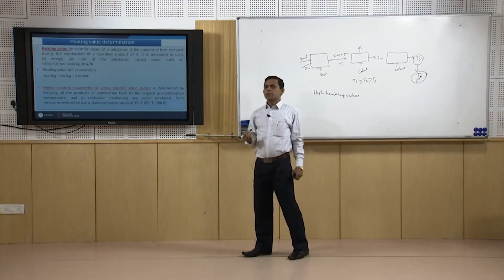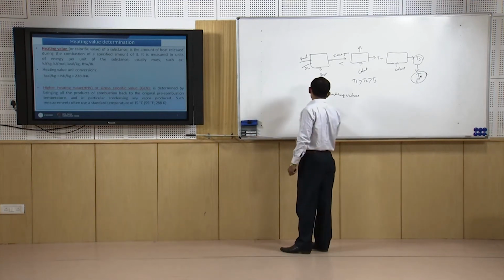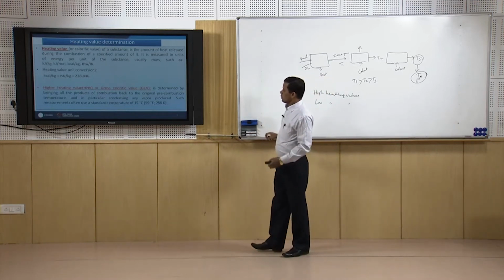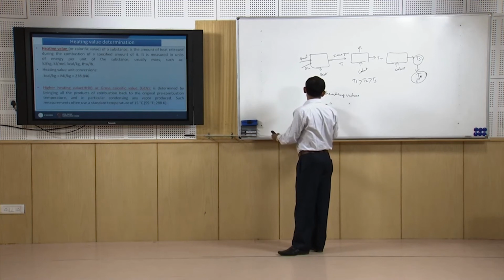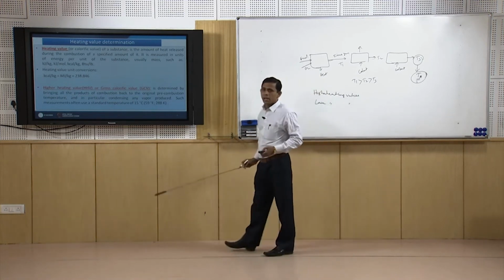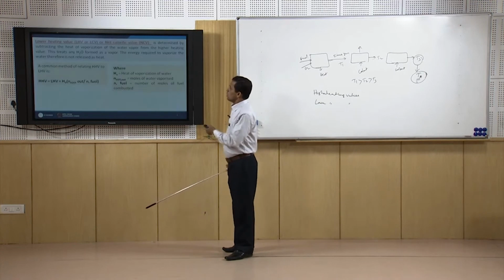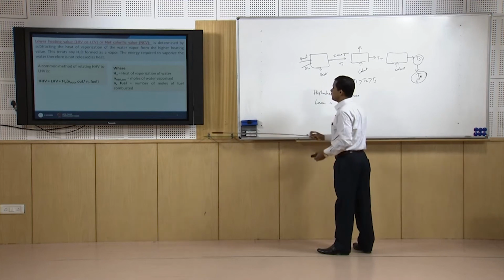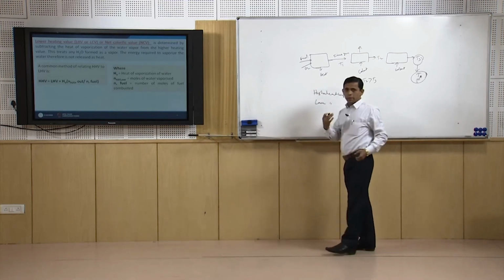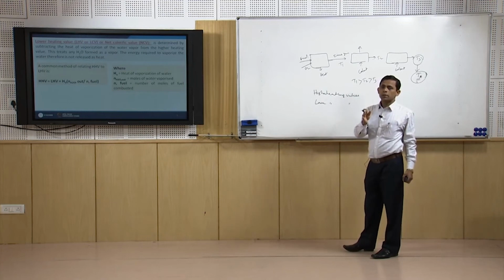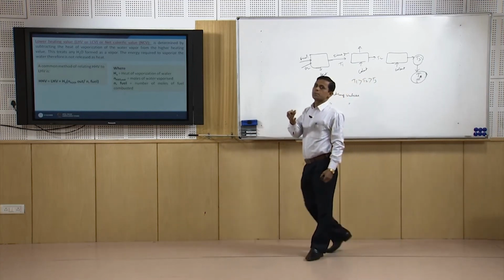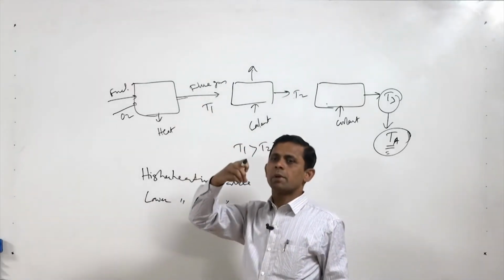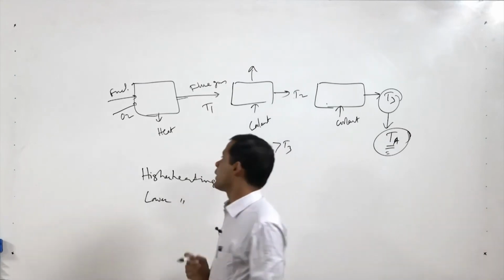So another type of heating value is also there, that is called low heating value. Sometimes higher and lower heating value is also called that way. So that lower heating value will be lower than the higher heating value, and how much lower it will be depends upon how much water has been produced during combustion, and that water molecules has captured some amount of heat for its vaporization.